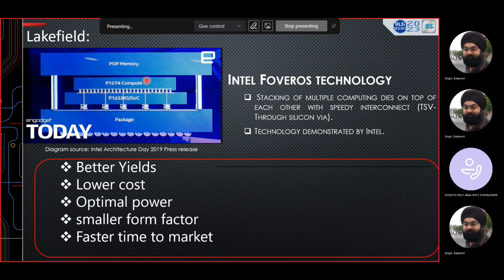The interference is also something to think about between the two copper lines today, what you are drawing. Let's say, what is the pitch? 2 to 5 micron, AP layer, the topmost layer, if you're talking about. Some of you are here, the layout folks, you know. 2 to 5 micron. I am not specific to any technology node. Here, we are talking about 25 to 50 micron, the gap.